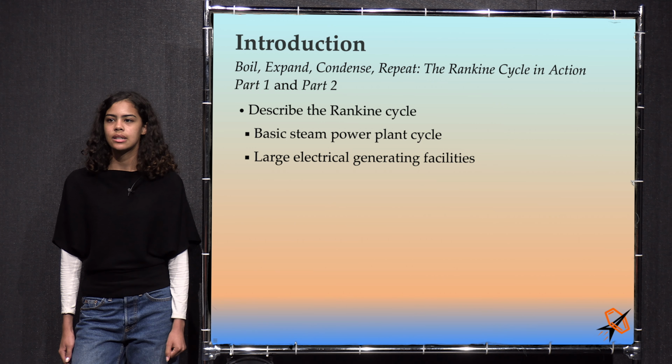Next, we will analyze the turbine. Since we're doing the isentropic calculation, we don't have to worry about the turbine efficiency at this point. So the shaft work is equal to delta H hat. We're going to assume the turbine is isentropic, so delta S hat equals 0, which means that S hat C equals S hat D. As we've done before, you can calculate the quality from the actual entropy in the liquid and vapor entropies. That gives us the quality at point D is 0.8074, or 80.7% steam.